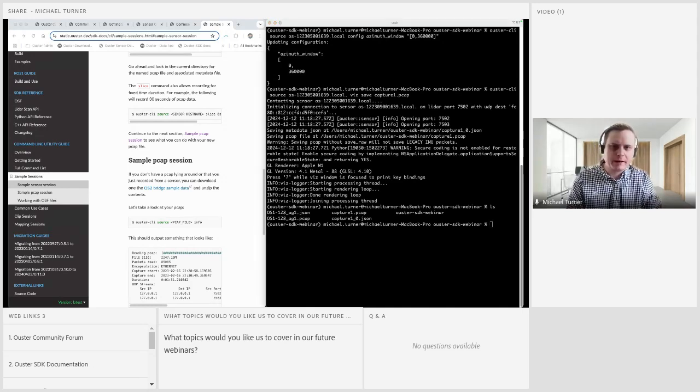Instead of focusing on the PCAP, let's do the same thing, but let's save it as an OSF. There's the OSF, the Open Sensor Format, fairly new in terms of how we're adding this to the SDK tooling. But there's some really nice advantages of OSF, which Tom will hopefully touch on a little bit, the basic concept and using it. File size is much more reduced compared to a PCAP, and you can also write custom data fields into the OSF when you're saving it.